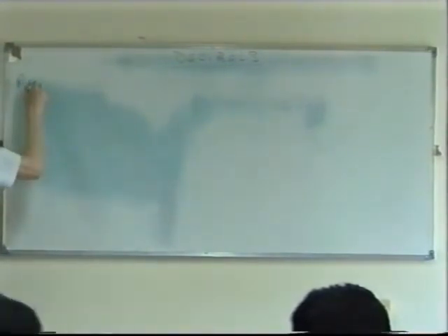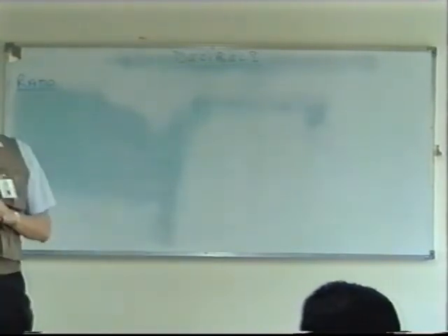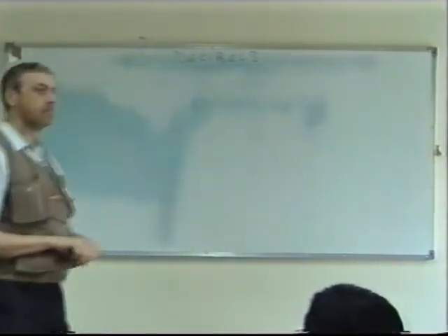Basically, what we're talking about here is a measurement of ratio. Now, what do we mean by a ratio? The word ratio. Yes, it's one number divided by another, basically, isn't it? You can talk about ratios in a number of different ways. Usually you talk about the ratios of two items or two values which are the same units. For example, you can talk about the ratio of voltages, or the ratio of currents, or the ratio of power. Now, when we talk about decibels, we're talking about the ratio of power.